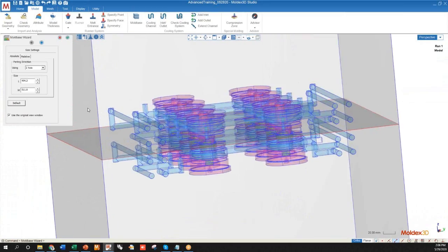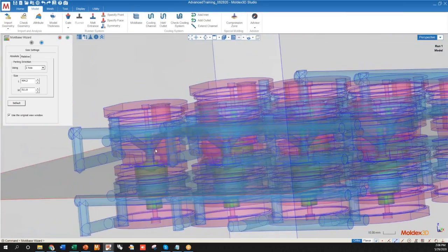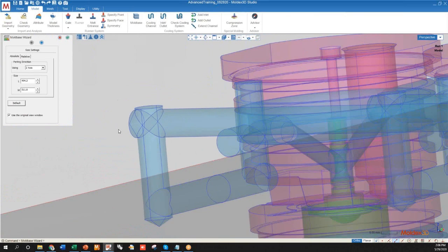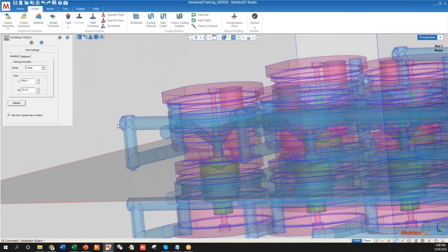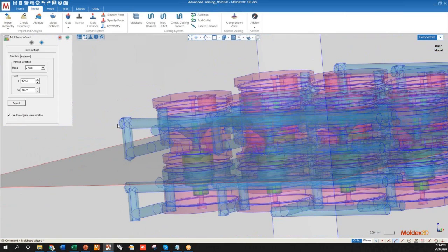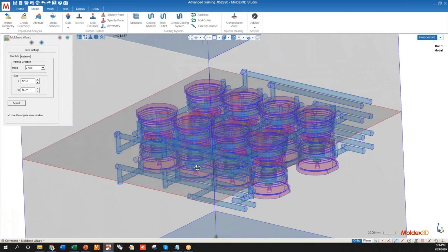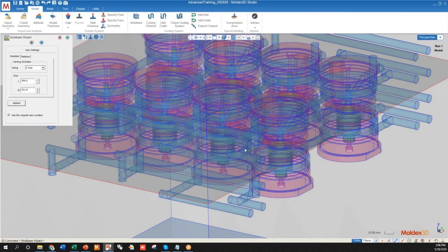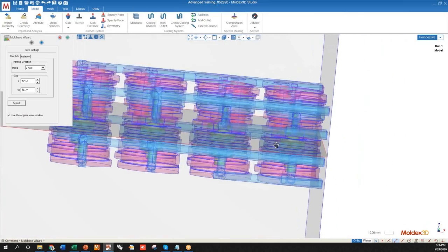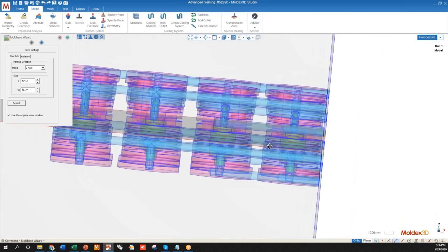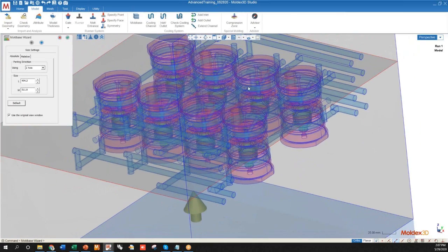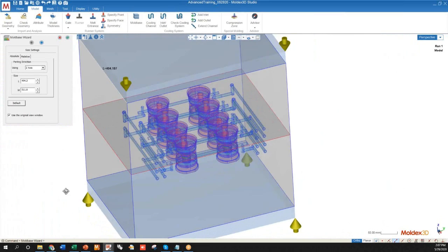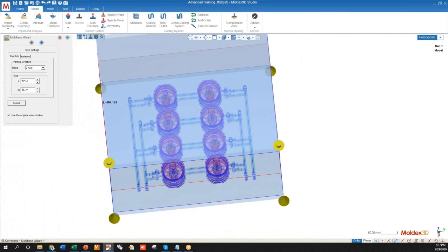So something like this over here is kind of a drill hole end, I'll say. So the drill hole kind of continues all the way to here. And that's okay for the simulation, but for the entrances and exits, or the inlets and outlets, we need those to be on the mold base surface. That's one of the most crucial parts of this whole modeling process, especially when you're trying to model everything from your mold design.